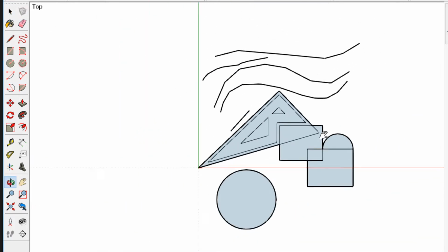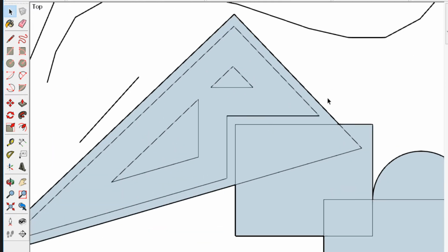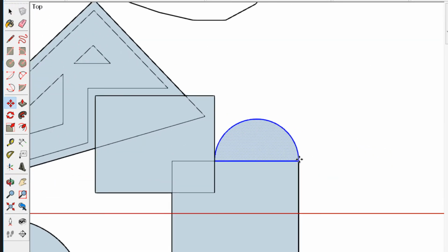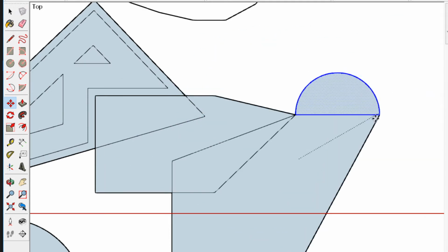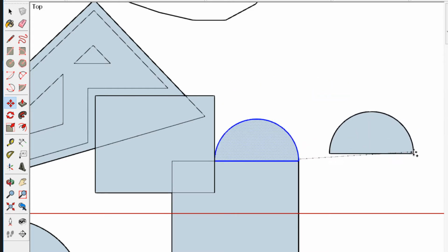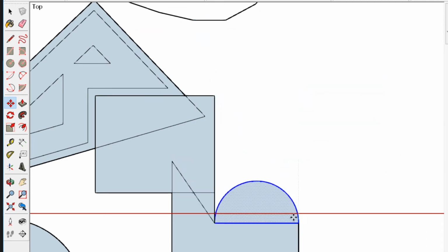This is very important when you want to make copies. So how do you make a copy? I use V for move, but the default here is M for move. Example, I select this, I click M, and I move it. Anything connected to it gets stretched. But if I hit Control once, it shows the plus sign and creates a copy. Okay? If I hit Control again, it goes back to the move tool.